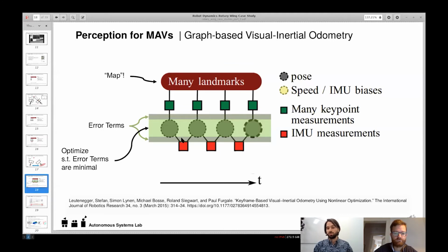In a linear Gaussian world, both of these should converge to the equal solution, but because we always have approximations everywhere, which one works better depends a bit on the use case. So if you need something that updates really fast, you're better off with a filter-based solution. If you need something that can optimize, let's say, a trajectory over the last 5 minutes and you want everything to be as consistent as possible, you would go with a graph-based one. I hope this somewhat answers your question.